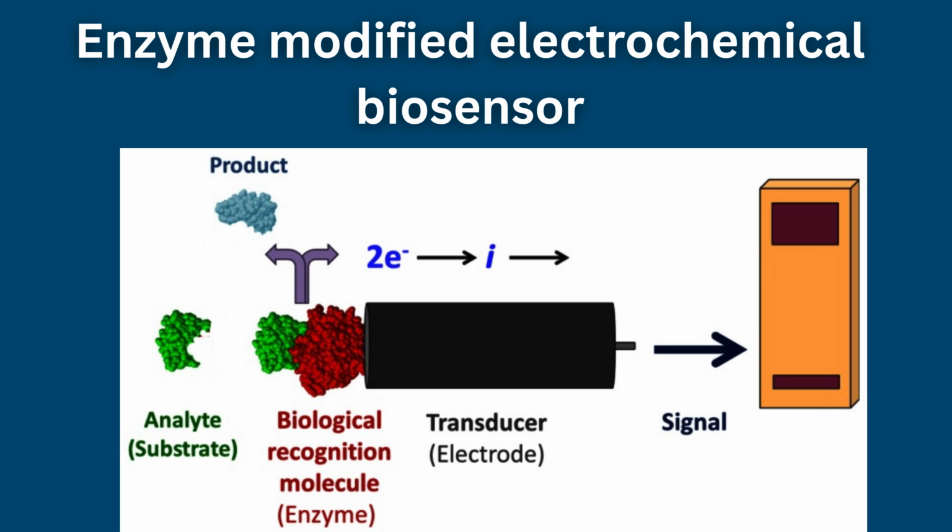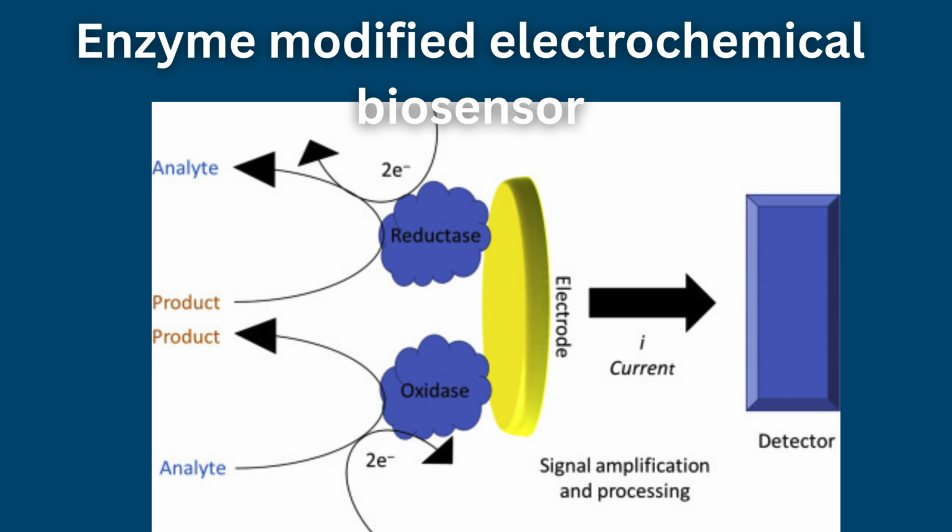Enzyme-based electrochemical sensors constitute another important category, leveraging the catalytic activity of enzymes to generate measurable signals. Enzymes accelerate biochemical reactions with high specificity and efficiency, often increasing reaction rates by several orders of magnitude. Immobilization of enzymes onto electrode surfaces enables the selective detection of substrates, with signal generation mediated by direct electron transfer or through redox mediators. The performance of such sensors depends on factors including enzyme stability, immobilization technique, and electrode material. Advances in nanomaterials have significantly improved enzyme loading and electron transfer efficiency, enhancing overall sensor performance.